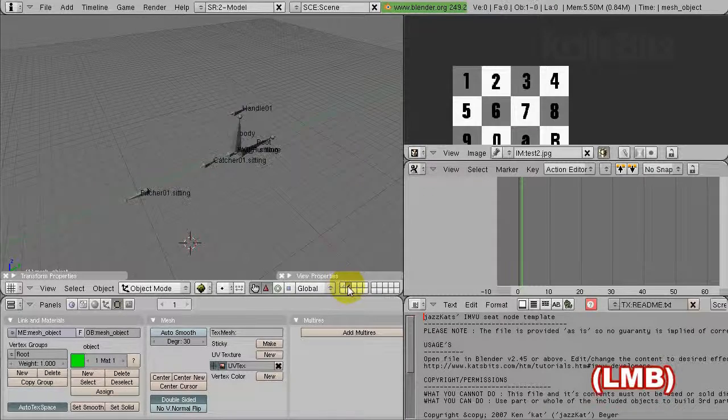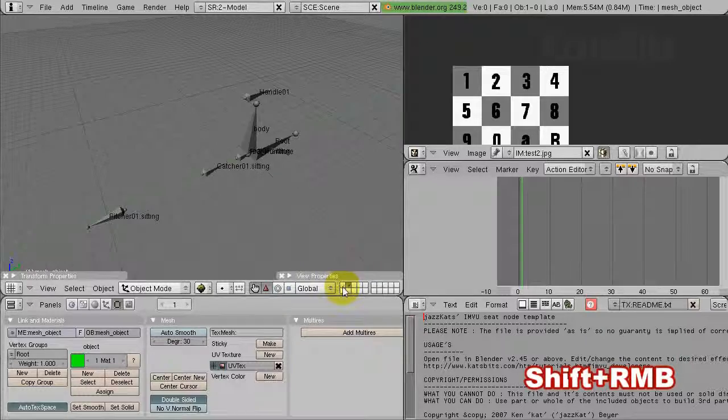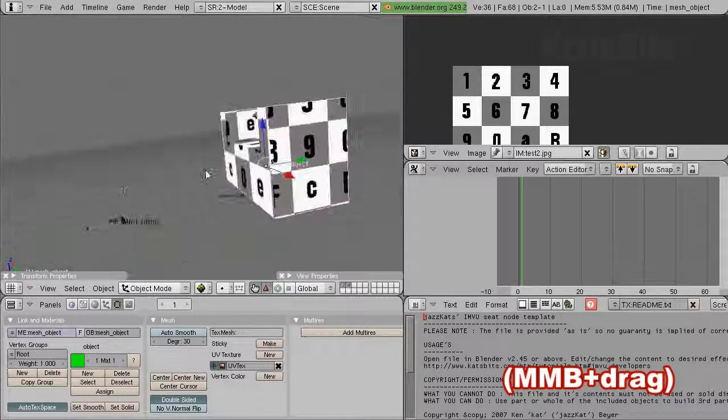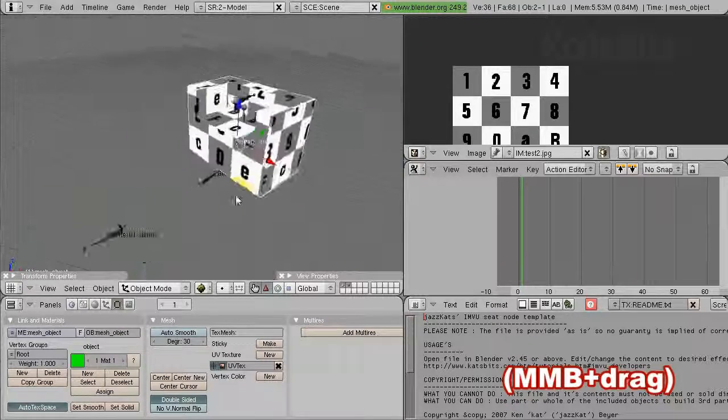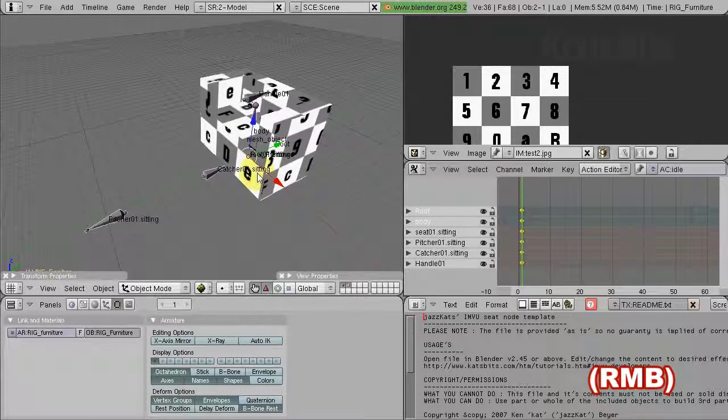We need to double check our other layers. We need to check that we only have the mesh that we need and the armature associated with it. The reason for doing this is that if we leave things in the scene, the exporter exports everything in the file. So before we do that, let's just save another copy.